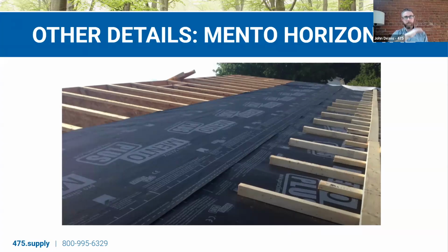And then doing the next layer, and then they'll tape that, do more short battens, leave them a little bit short so that you make sure you get the overlap to be able to tape that together and just work your way up the roof. I've even talked with some folks who do the whole thing all at once. You put the membrane down, you put the battens down, you sheathe that first layer, and you just keep staggering everything as you go up.